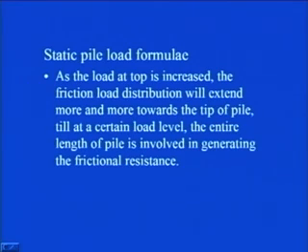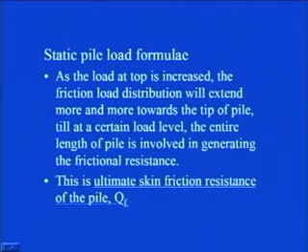One situation will come when the whole length of the pile shaft will be causing that whole friction load. In that case, that particular resistance is called ultimate skin friction resistance of the pile, and we represent that by Q subscript F, that is QF.